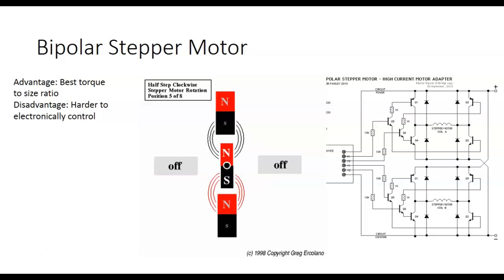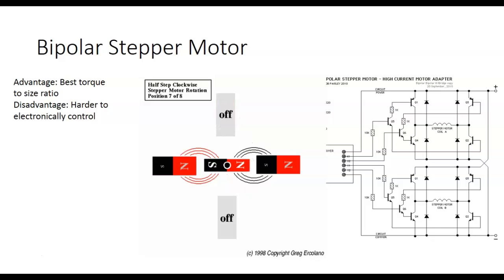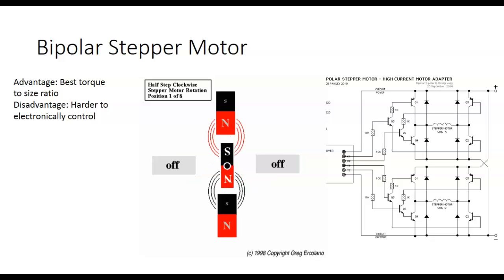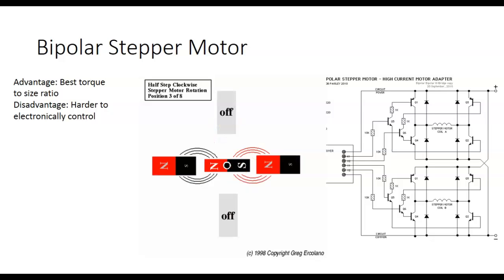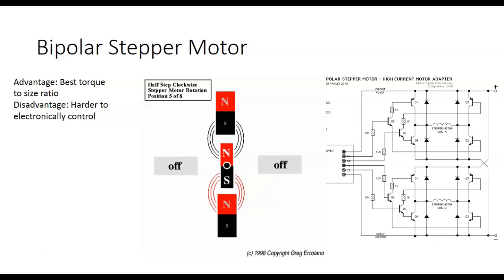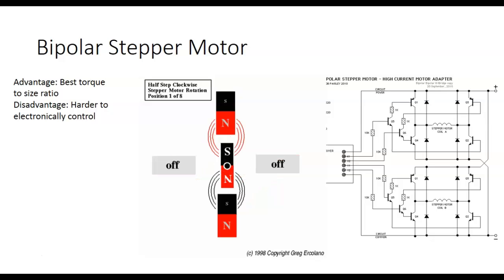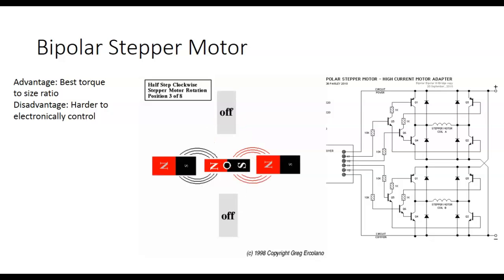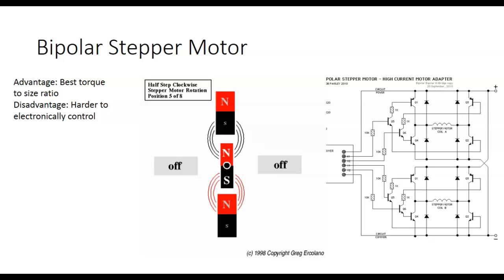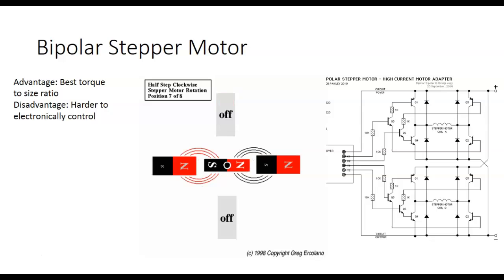Normally we show that where I get it moving, I flip the power off, and we turn it back on. It'll start single stepping until that inductive sensor clears. Then it steps back so many steps, and then it's lined up. So if you wanted to screw that up, just move that inductive sensor, right?